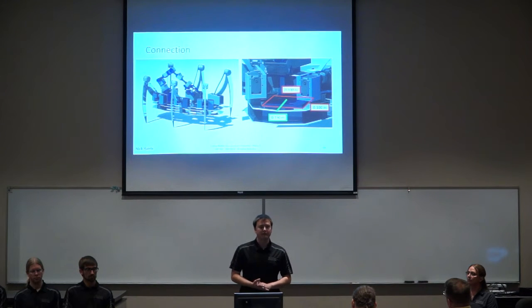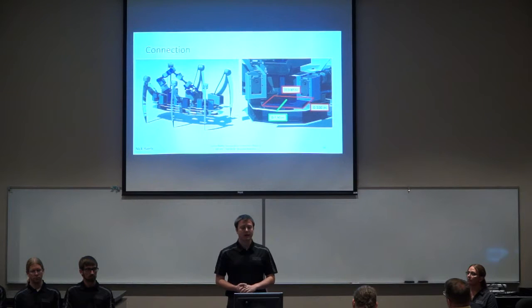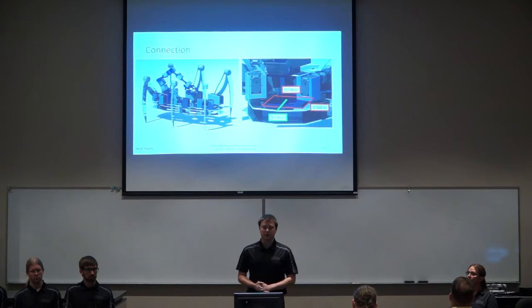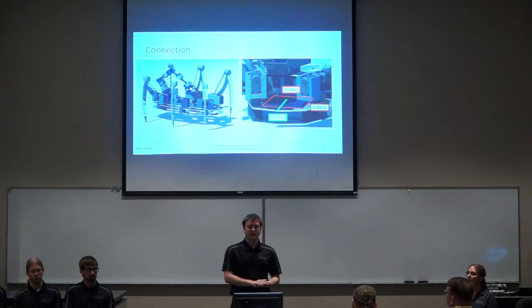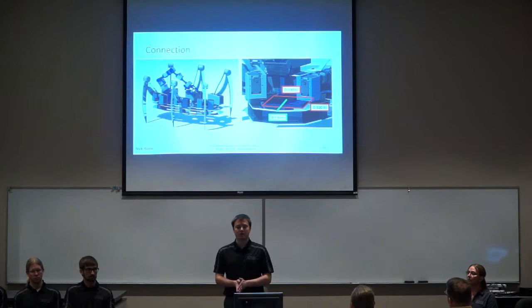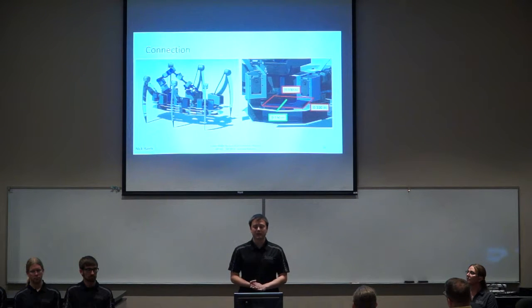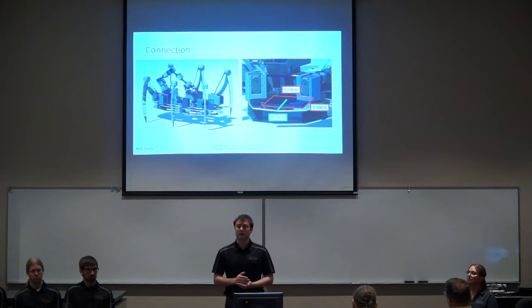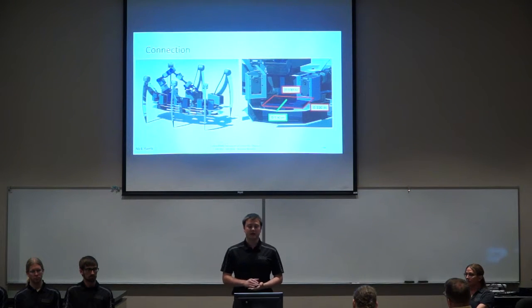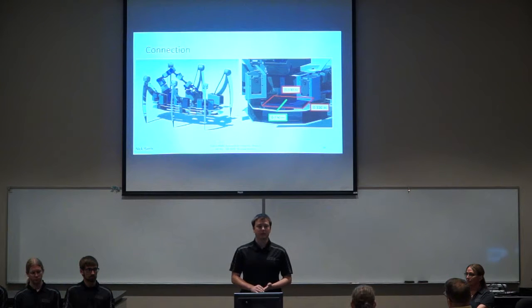And here is the actual physical connection between the hexapod and our tail. The left image is both of them together, and the right image is a zoom up coming from the backside of it. You can see that we are centered 0.15 meters from the back of the hexapod, and it is encompassing an area of 0.1 meters by 0.1 meters, and that exactly meets our specifications.